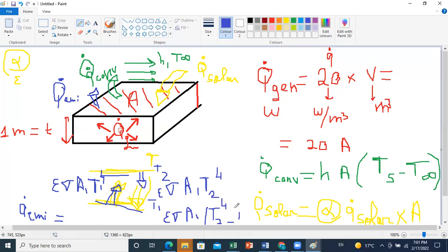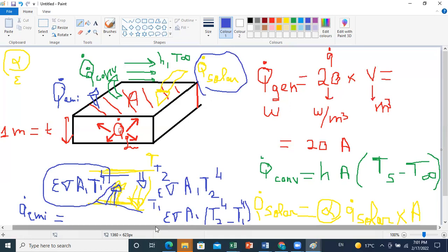Here it's a little bit different because instead of giving you another surface and giving you the temperature of the surface and doing a net flux of radiation, you still have radiation from the surface. So this flux is still present, but the received one is replaced by Q dot solar that is absorbed. This is why you should know how this formula was derived: to write it, I should have two surfaces and I should know their temperature. If I just have one surface, it can just emit. It can receive, of course, through other forms, heat fluxes. But if it's alone, it can emit by radiation without receiving. Here it's receiving in solar form, which is also a radiative exchange.